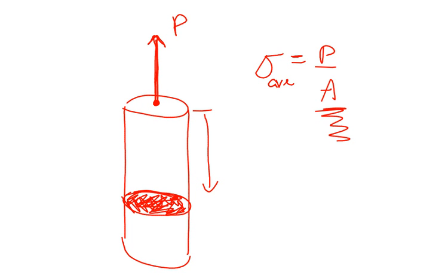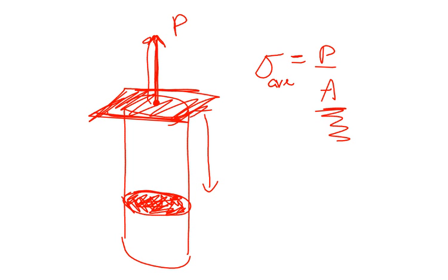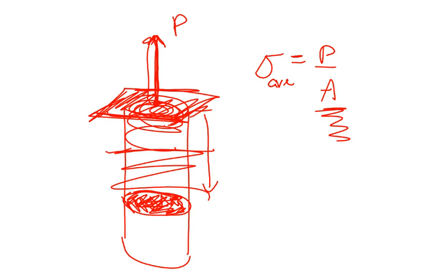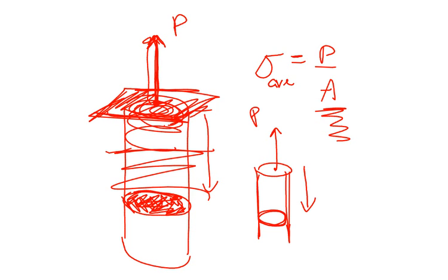Now, if I were to put a rigid plate and then apply that force P right on that plate, then the force is evenly distributed right from the start, at every single cross-section. But if I apply P as a point force right onto the structure itself, like I showed earlier, then St. Venant's principle says I just need to get a little bit away from the point of application of that force, and that force will be evenly distributed.